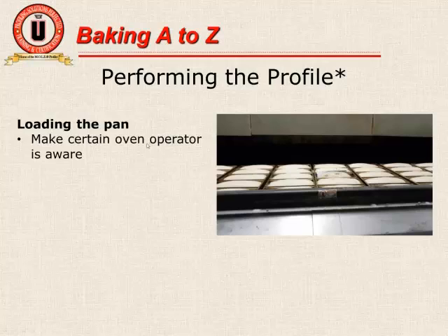And if you are the oven operator, bless you, because most oven operators don't profile. They usually save that for someone else to do. However, oven operators can do this, but if you're coming down onto a line, make sure you've connected with the operator first, and always ask for assistance. Don't do this alone. Have at least 2 people involved in this process to help you out.